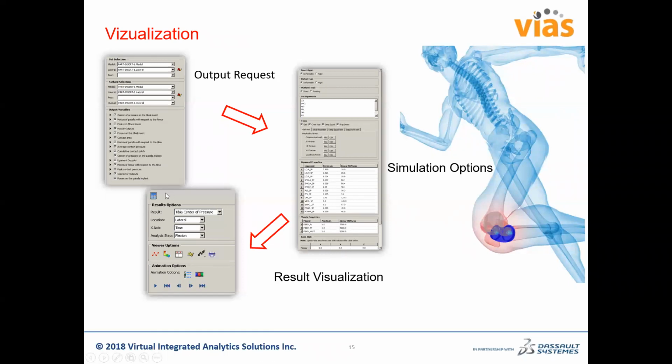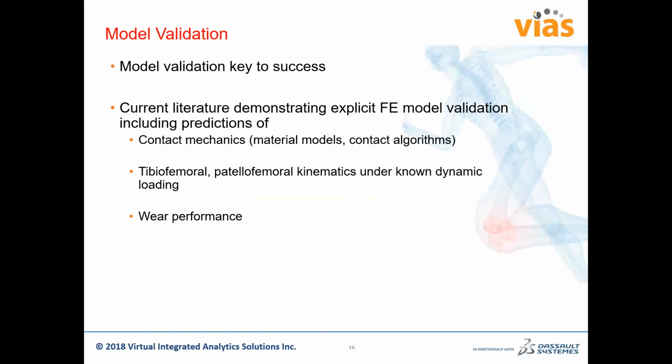Then, if you see a calculator button here, once you click on that, AKS will do the calculation for you for all those outputs which are required from a certain workflow but are not available by default within Abaqus CAE. That makes life very easy, as all the post-processing is done by AKS, and you really don't need to write any scripts or anything for that.